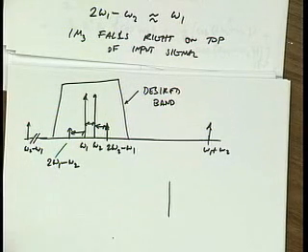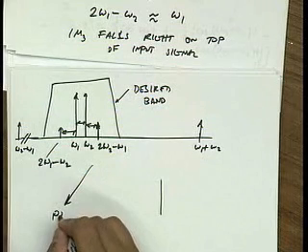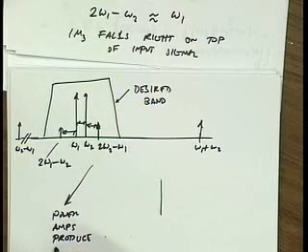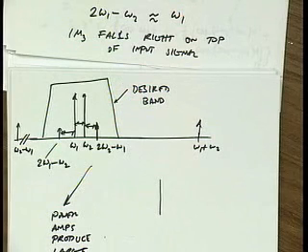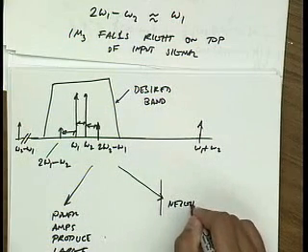Okay, question? Yeah, but here we don't have the problem that the signals causing the intermodulation are much stronger or can be much stronger than the signal itself. That's a good point. That's a very good point. Now there's two scenarios where this still does matter. One is in power amplifiers, because they produce large signals. So a power amplifier will self-interfere. In other words, you put in one spectrum and out comes another spectrum that has components that weren't in the original spectrum. And then the other scenario is you still have basically neighboring channels.